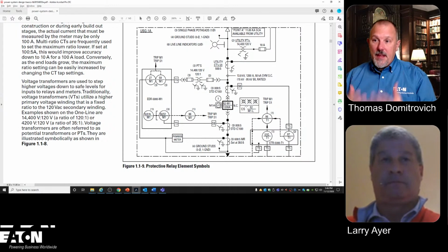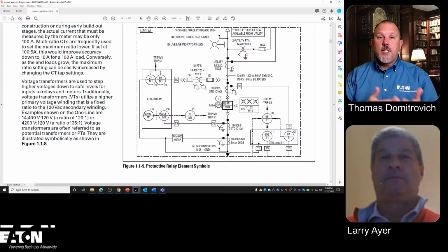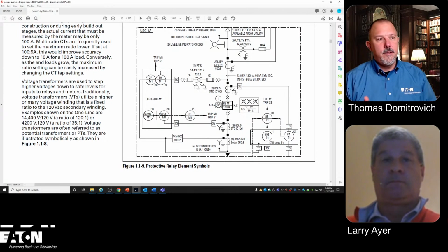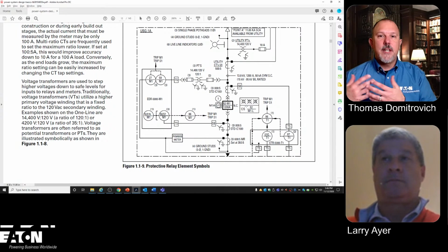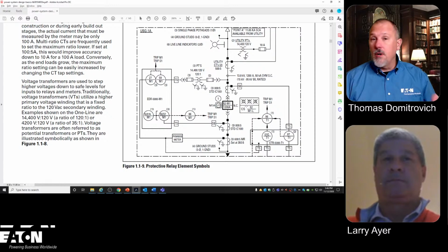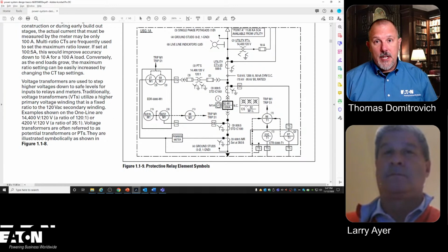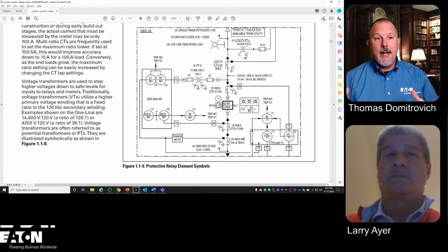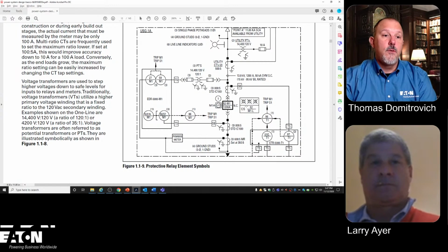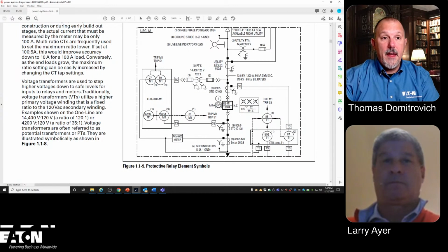And if we think about using a 90 degree C conductor at its 90-degree C ampacity, as opposed to using a 90-degree C conductor at a 75-degree ampacity, it's around heat, right? And there's a lot more copper in these medium voltage applications. There's a lot of space, and to an extent, you're correct. They terminate on bus typically. That's bussed into the circuit breaker. So that may play a part of it.